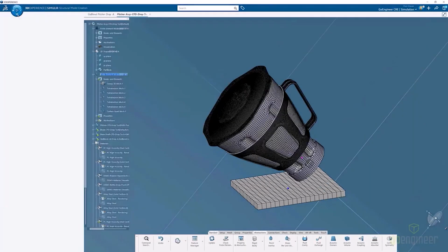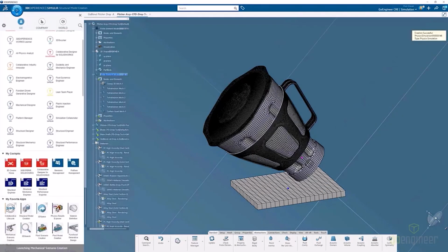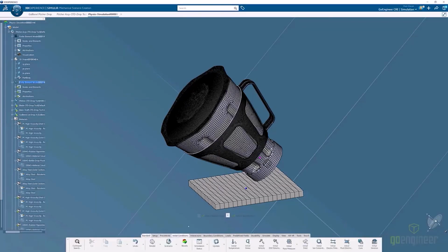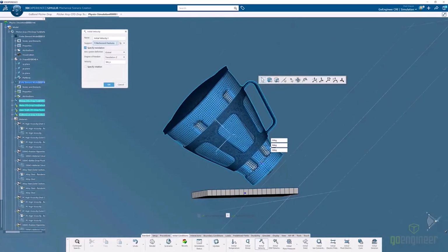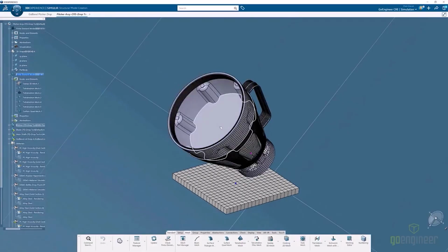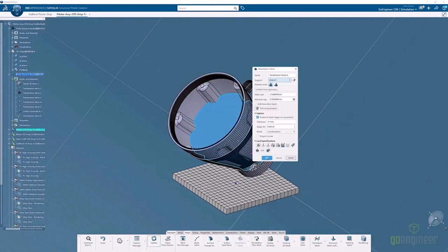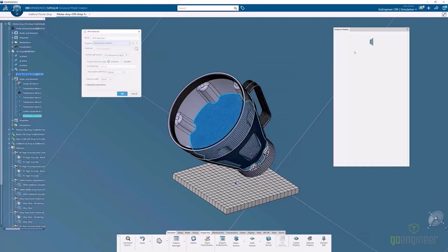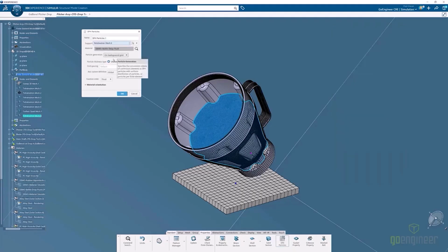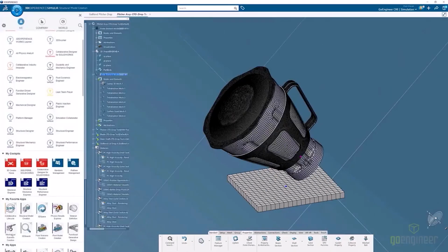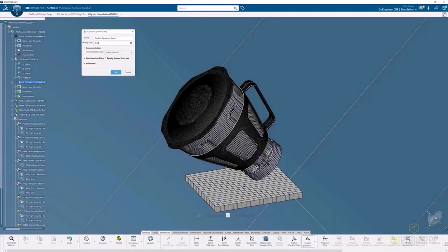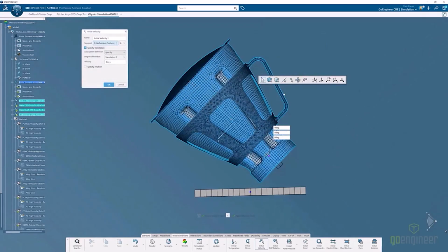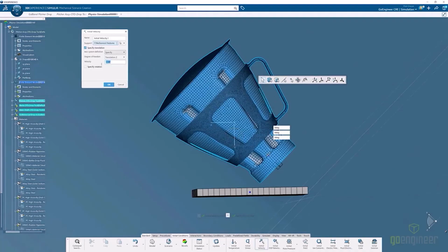From there, we're going to go ahead and set up the boundary conditions. So inside of 3D Experience, what we can see is going to switch over to Structural Mechanics Engineer, and he's going to start adding in things like the initial velocity. He added in the general contact into the model, and this is actually pretty interesting what he's doing here. He's adding something called smoothed particle hydrodynamics. So this is called an SPH element. So he's able to take those bodies that represent the fluid inside the pitcher and add to them a way of finite element analysis, treating them as though they are a liquid.